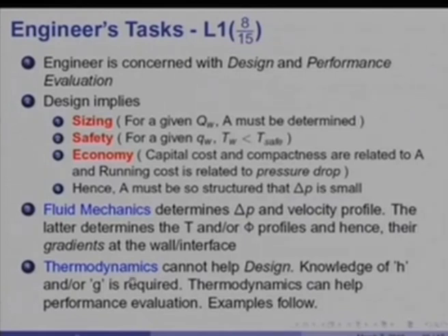Note that thermodynamics cannot help design, simply because thermodynamics deals with the change of state and not with the rate of change of state. Therefore, if you want to design any practical equipment, what you need to know is the rate of heat transfer per unit area, per unit time, and that can only be determined with the knowledge of H or G, as the case may be, whether one is considering heat transfer or mass transfer.